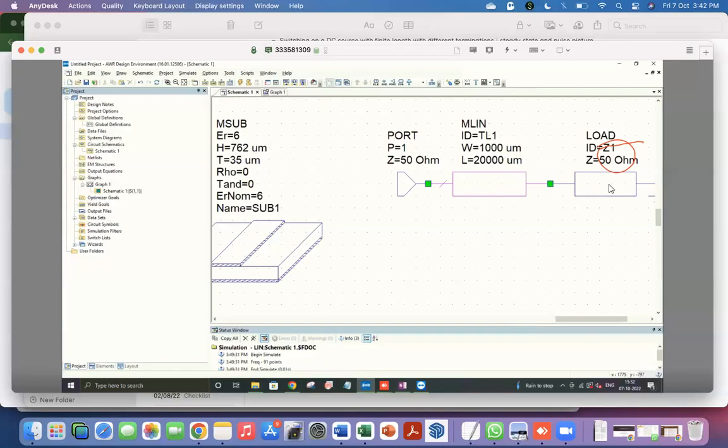So there are a few possibilities, right, which we have learned. Maybe this is behaving like an impedance transformer at those frequencies. But the thing is, this is already 50 ohms. So it cannot be a lambda by 4 transformer. It cannot transform 50 into 50.